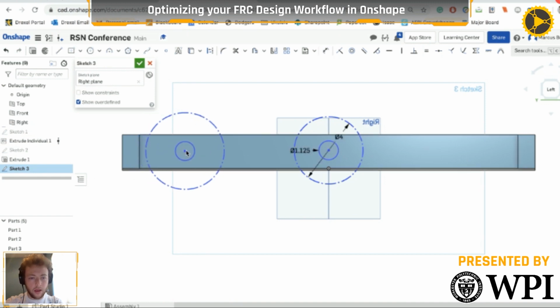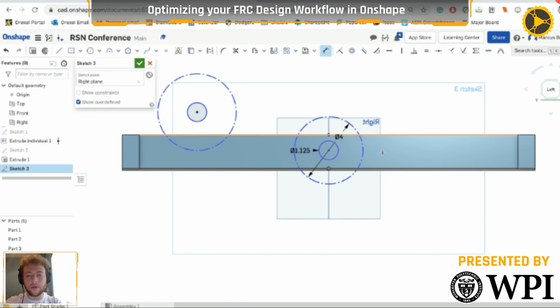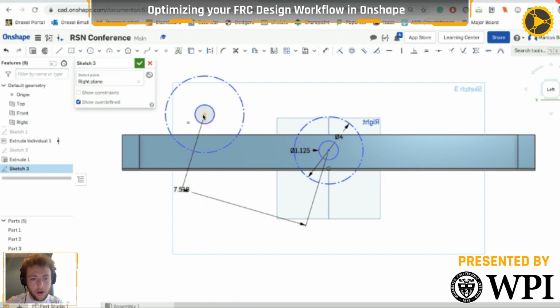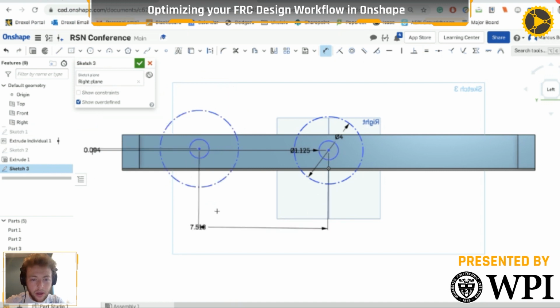I'll set the center to center distance between those, and we're just going to assume that it's whatever. How about 7.5 plus 0.018? 0.018 is like a center adder, so we don't need to tension the chain later on. And then I'll also set up the height to facilitate the wheel drop, say it's 332. Okay. Oh, look at that.